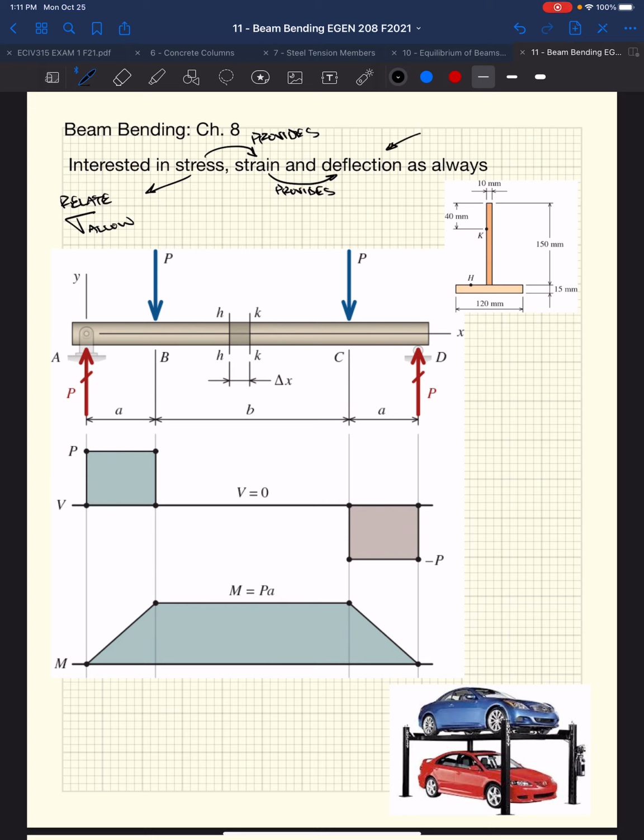And if we have indeterminate systems, like in torsional systems and axial systems, it was this force deformation relationship and this relationship of deformation in our system, right? We had parallel systems, we had systems in series, we had systems that were connected, that were geometrically related to one another, right? Similar triangles and things. If one deflected, say, half an inch, the other one would deflect twice that much because it's twice as far from like a pivot, okay?